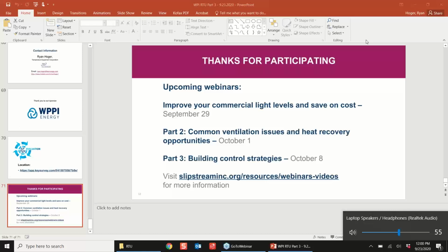Here's a view of the economizer. This is a modern economizer. If you remember from session 2, we said if the gears are on the outside, that's a pretty good indication that's a low leak economizer. And you probably can't see it, but there's also seals on the edge of these dampers.